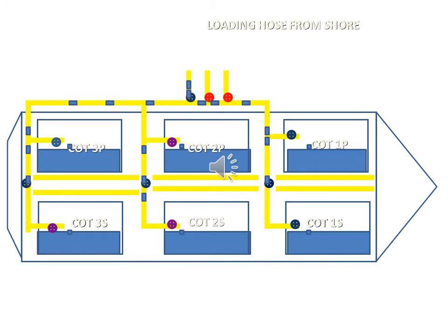If the vessel is listing to either port or starboard side, stop loading on the side where the ship is listing. For example, if the vessel is listing to port, then stop loading on the port side.